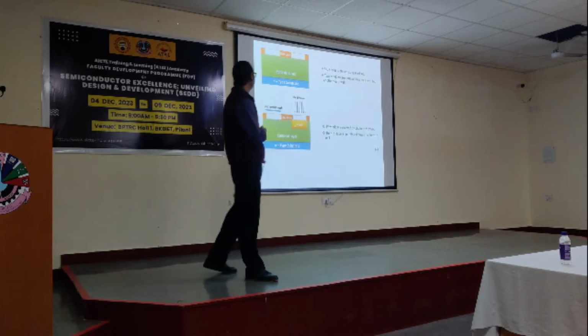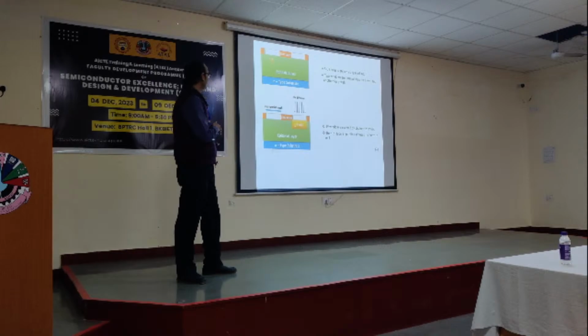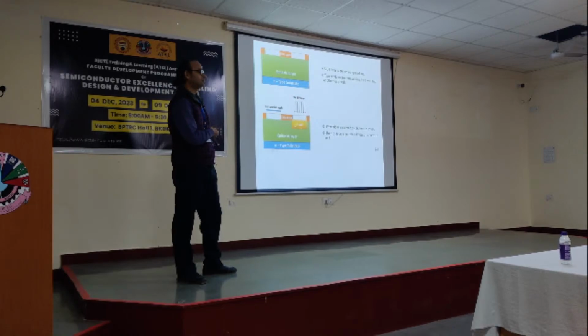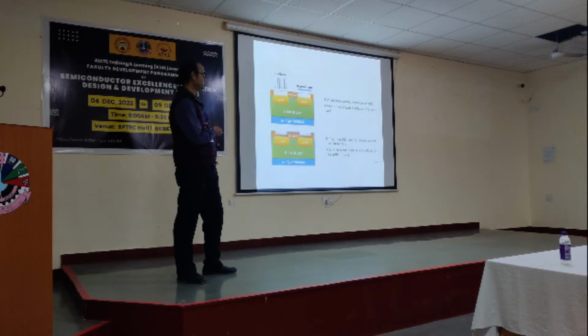So these two portions are etched with proper masking. Now I will put a photoresist here so that nothing is implanted here. Now we will implant P plus from this side. P plus means we want to make a P-well. The next step will be the reverse of this: apply photoresist and a photomask here, which will prevent the dopants here, and then we can make an N-well.